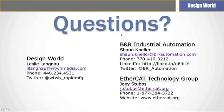Okay. This one is for PowerLink. How is the bus topology different from daisy chain? The questioner said that you showed a diagram for a bus. The bus configuration, yeah, it would really be done with hubs. So for example, you'd have maybe a 3-point hub come in, and then you'd have a drop line from each of the hubs each time you want to do a bus. So it's really a similar thing to the star configuration. It would just be multiple hubs each time, and obviously each one of those lines could be 100 meters as well, which is the standard Ethernet length with the Cat5 cables, etc.